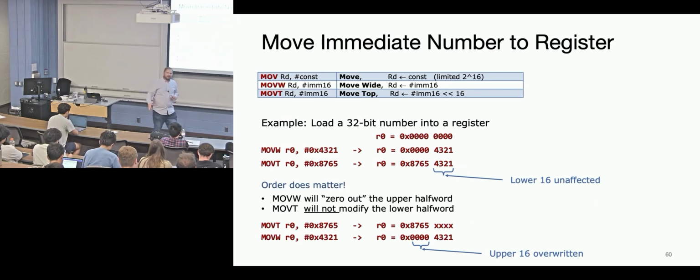So regular move doesn't zero out the top 4 bits, right? Correct. But they're effectively the same thing apart from zeroing out, right? Oh, sorry. When you say zero out, it's going to put the immediate number in there. So those top 16 bits, I misspoke, those top 16 bits are part of the number. It will be zeroed out: because its limit is 16 bits, the top 16 bits will be zeroed out. Correct. So it's the exact same thing as move W or no? Yes.